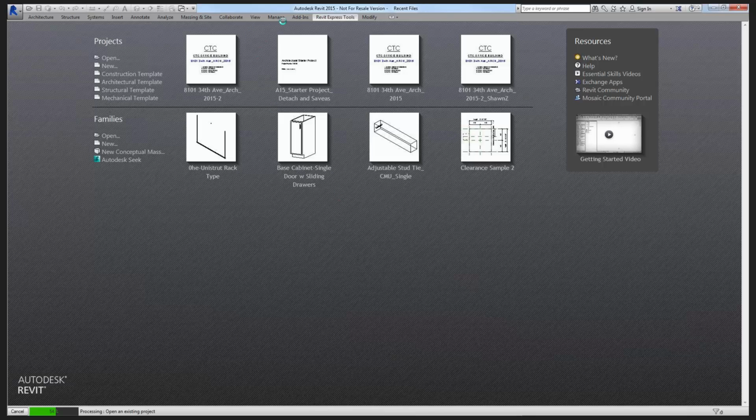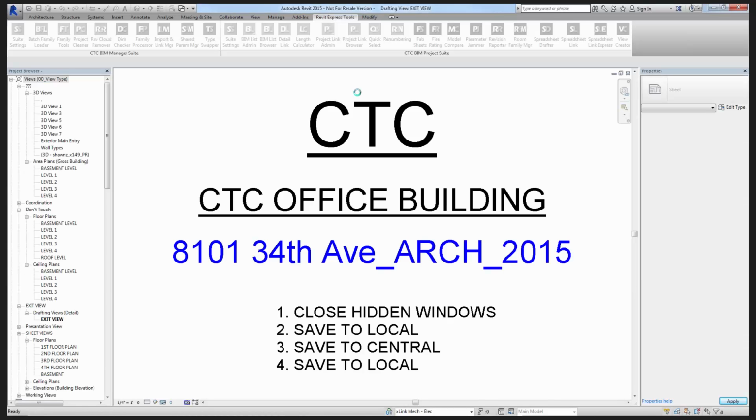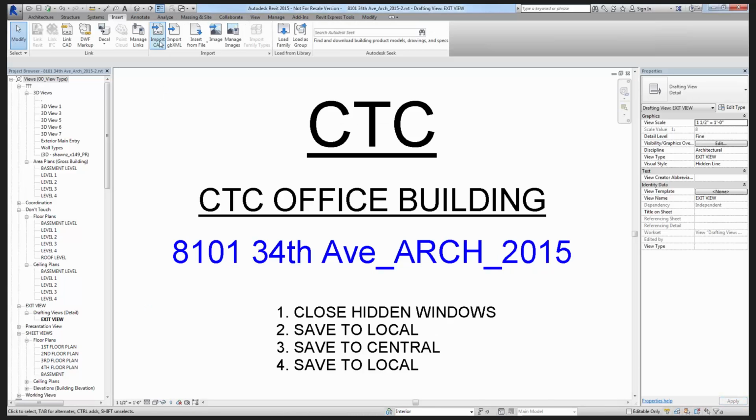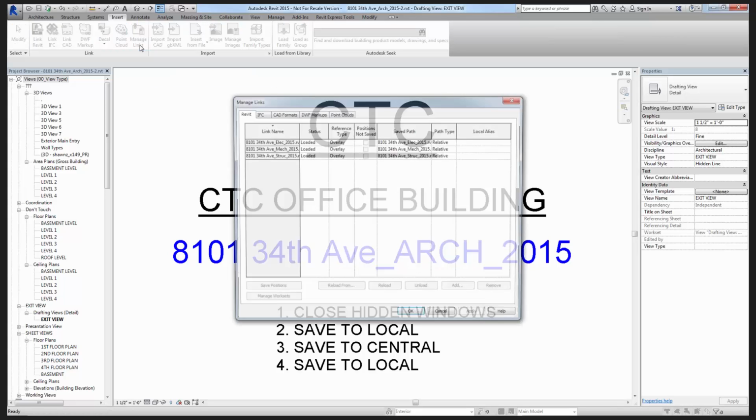This model has become its central file in its current location. When you use that reload tool from the Revit Express tools, it modifies, it augments that central file a little bit externally, and it makes you resave it when you open it the next time as a central file. So it's an important step to do before you start letting users into the model. So at this point, once this is fully opened up and it's saved, because it's actually running a save command right now, let's go take a look at the traditional out-of-the-box import links or manage links dialog.